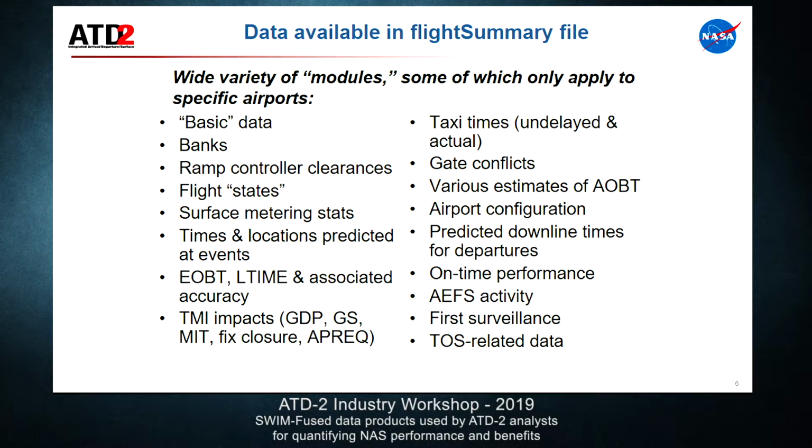Those are some of the things we're trying to pass on as lessons learned. For example, we capture what's called the pilot ready time, which is not a data element that would be in TFDM. If you're an operator trying to understand how much fuel savings you're actually achieving, and you don't have that pilot ready time, you don't know what the actual gate hold was, and so you're left to guess what type of fuel savings.